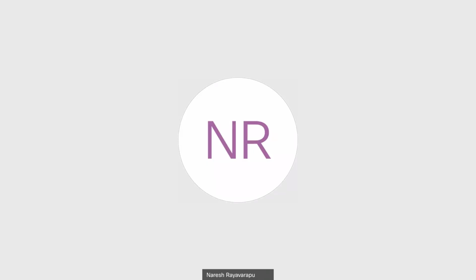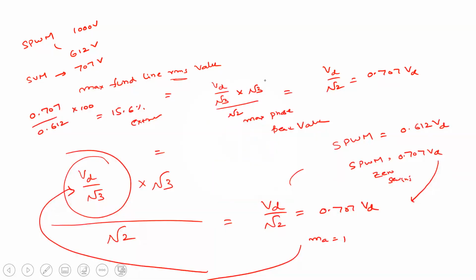So in the previous class, we started discussing the space vector modulation technique for two-level three-phase inverters. We calculated the dwell times using the volt-second balance, and we defined the amplitude modulation index to control the inverter output voltage. And we found that by using the space vector modulation technique, the DC bus utilization can be improved by 15.6% when compared to the sine PWM technique.